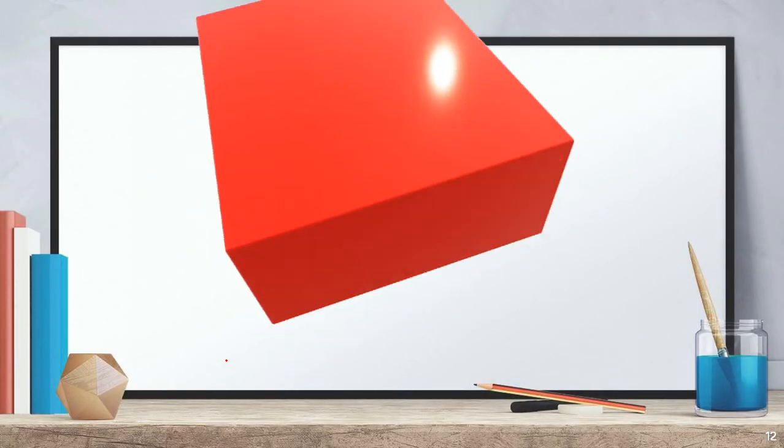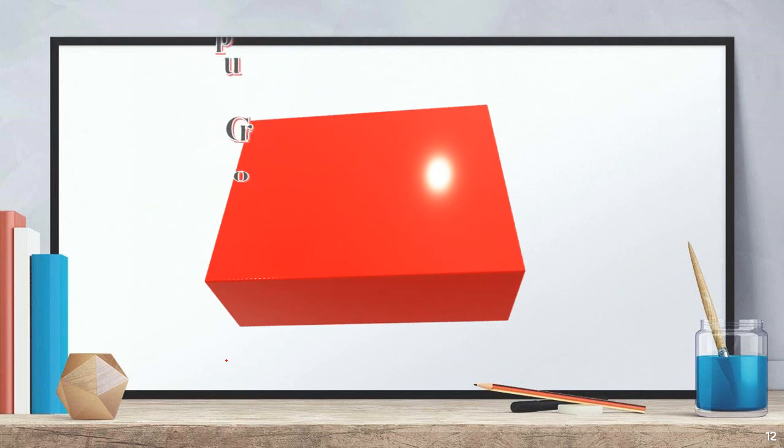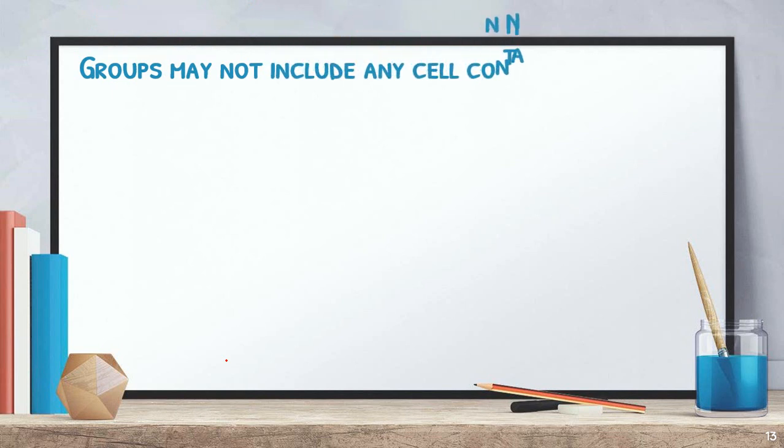Next we move on to how to do grouping of the cells. The second part in the KMAP is that you have to make groups wherever 1 is present. From that only can we simplify the equation. For this we can go with a step-by-step procedure. There are some rules and regulations for grouping. We cannot simply do any type of grouping. The first condition says that a group may not include any cell containing 0. That means if you want to do grouping, it should contain only 1s.